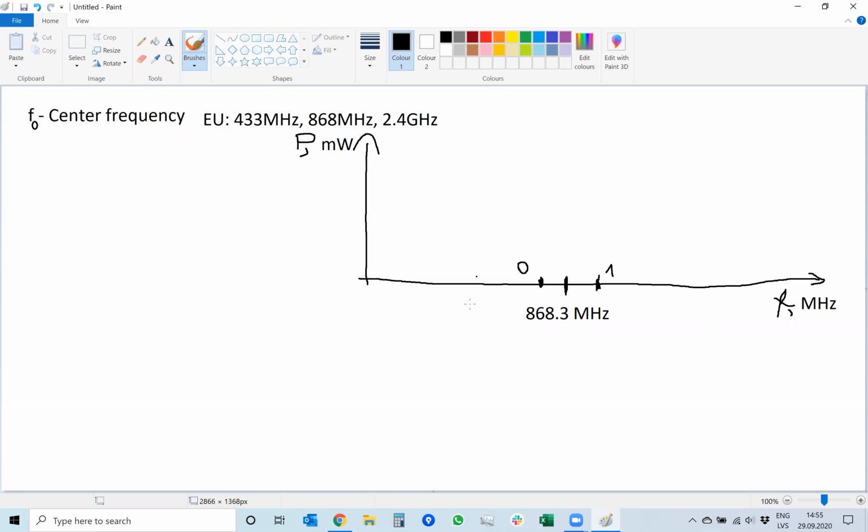And this way, if there's no signal, it means that there's no message. And if you want to send a message that starts with 0, you can do it. You just send a signal at a little bit lower frequency. So for example, if I want to send 0, 0, 1, 0, it means I send 2 times signal at 0, and then I move the transmitter to this higher frequency and transmit 1 for that moment, and then I move it back to 0. And when I have finished, I just switch the transmitter off completely, and the receiver knows that there's no signal, so the message has ended. So this is a much better way to send information.